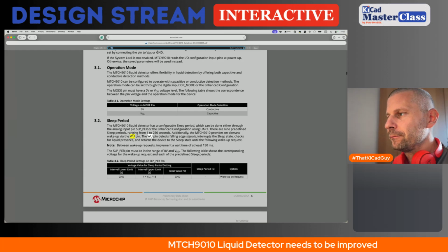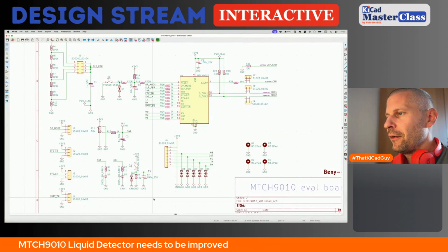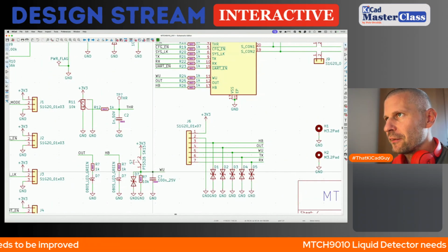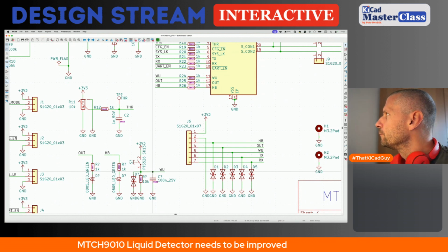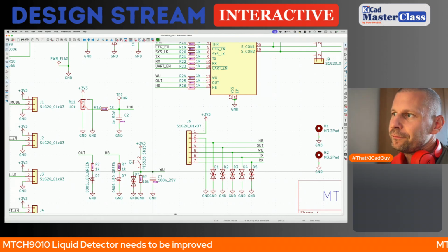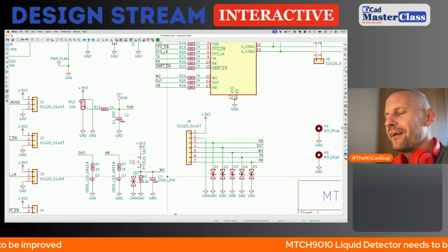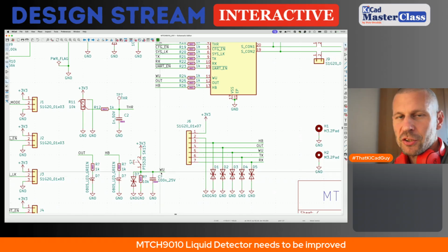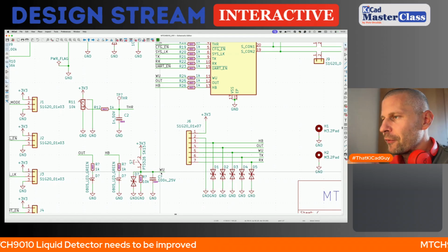Okay, so I have to change the schematic because it detects the falling edge signals. Frankly, I believe more in the missing negation mark, like the overhead line on the wake up.